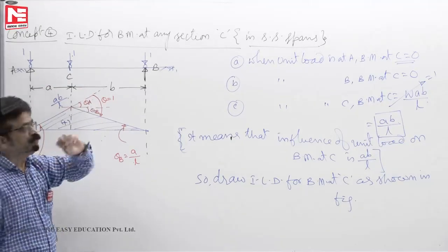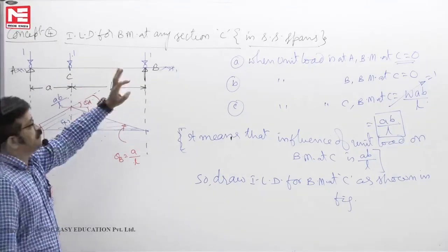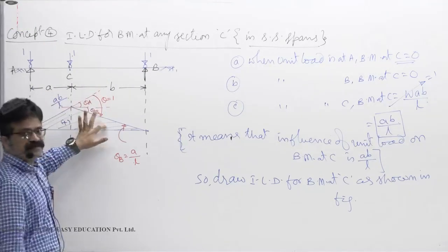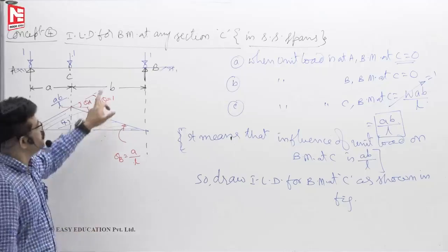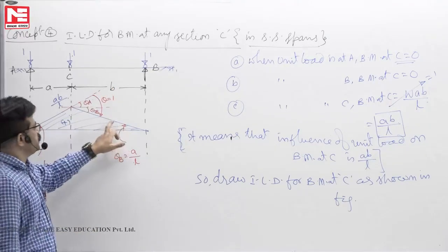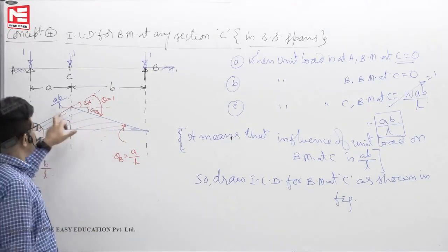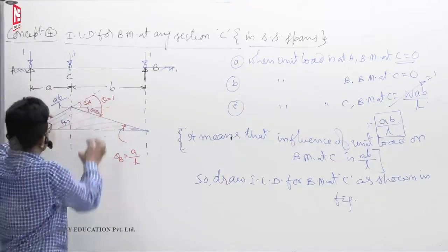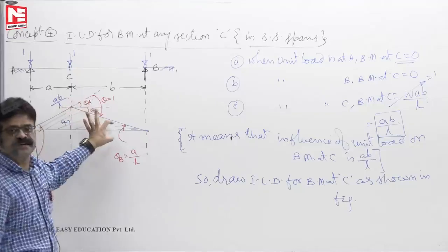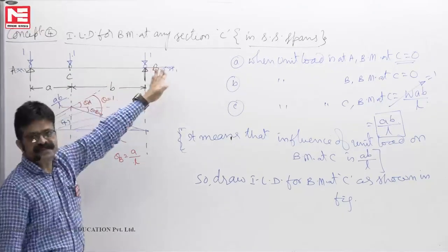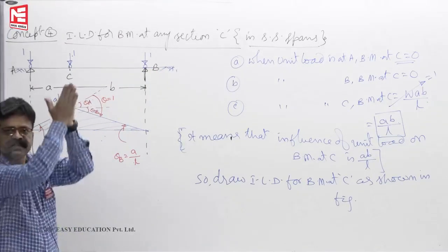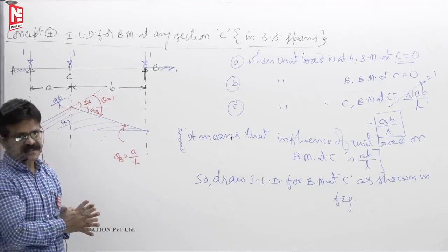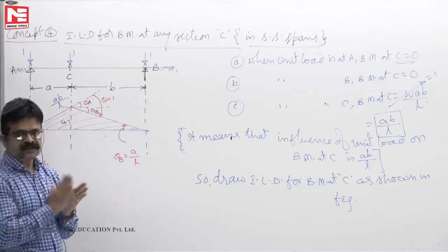If two loads are moving on the beam, then greater load at greater ordinate, lesser load on the less slope side, that means where span is more. This slope is mild, here steep slope is there. So if you keep the load here for same distances, here ordinate will be less, ordinate is more. So keep the lesser load on the right side, greater load on the C itself. Then you will get maximum bending moment at C. That is one load, two loads are over.